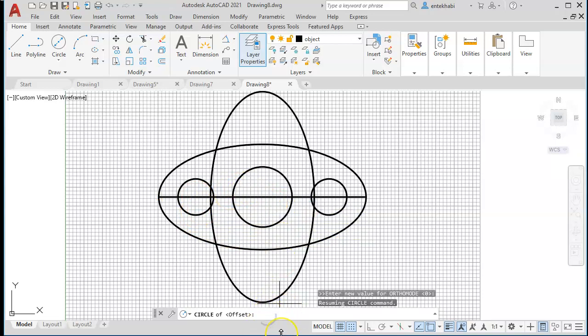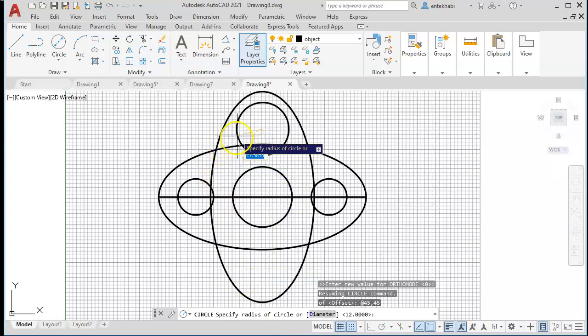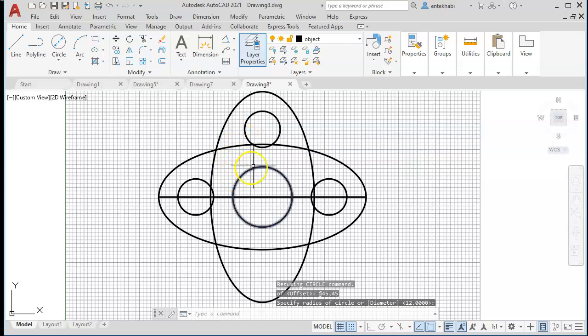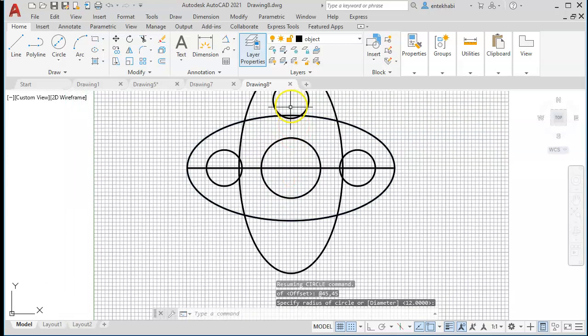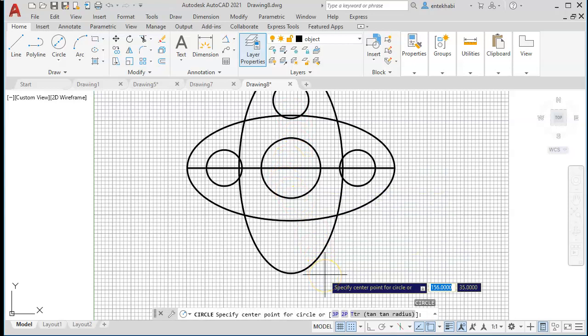Then it's going to ask me where, and I type at 45, comma 45. I expect to be in the right place this time, and the radius is still 12. Okay, now before I forget my reference point, I'm going to repeat this one more time. At. This time I'm going to use the polar system. I'm going to say go to 90, angle 270.